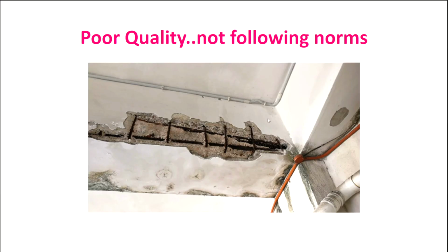What you can make out from this? अगर ये आपको दिख रहा है तो इसके अंदर में क्या प्रॉब्लम दिख रहा है आपको? It's falling, sir. Falling of concrete because of no proper cover. Yes, it may be a possibility that the cover is not provided of adequate thickness. ठीक है ना? And the grade of concrete, again we are not aware. The quality of concrete, yes, poor quality also can be an important reason for all these things to happen.